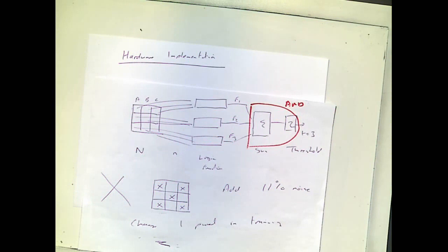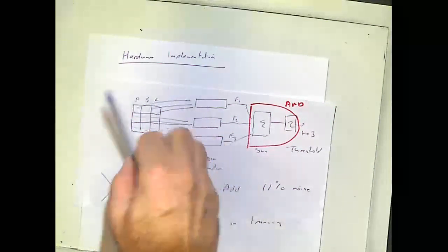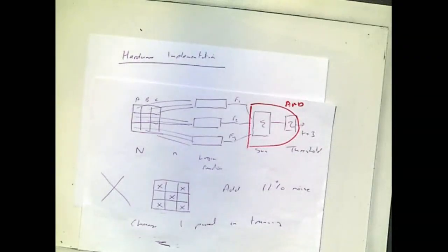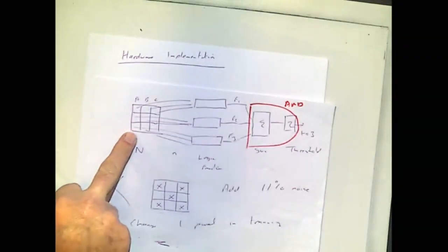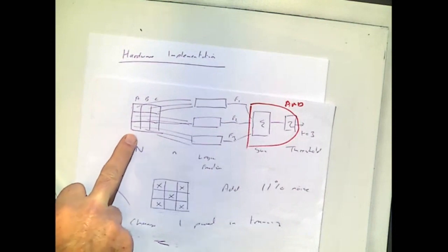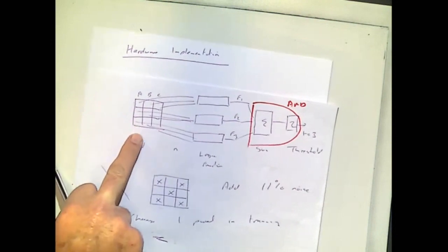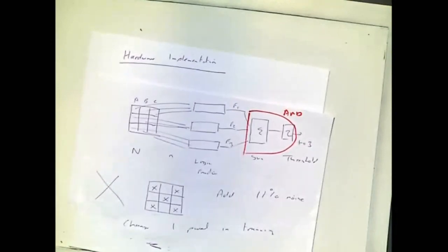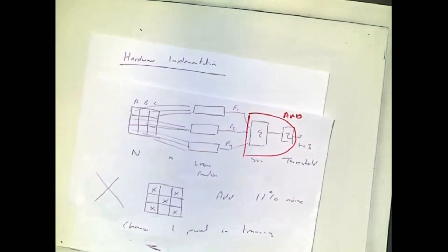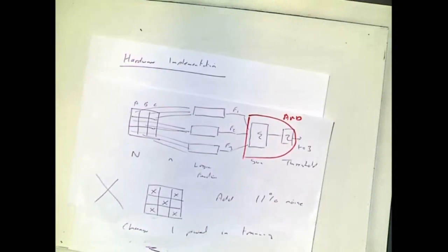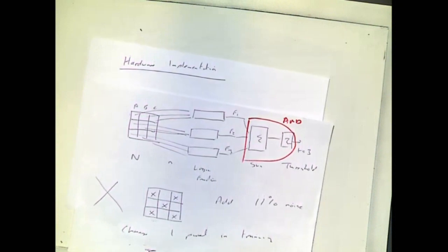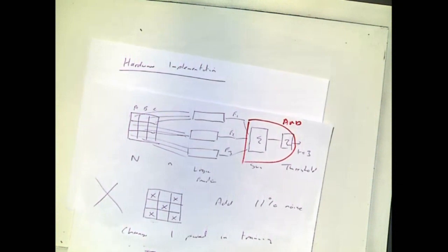Access time. So, if you were building this system and you did it as this schematic suggests, a parallel system, you would find this would take milliseconds to update because it's coming from a camera. And when you've got the information in that image stored in the frame store, accessing these memories would take microseconds. So there is a completely imbalanced duty cycle. The data is being collected slowly, and as soon as the data is there, the response is almost instantaneous.